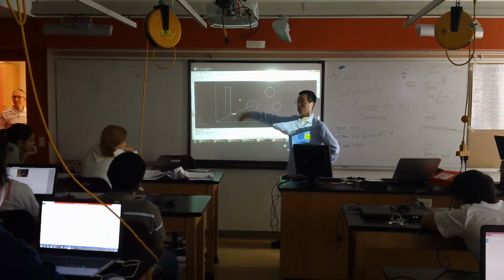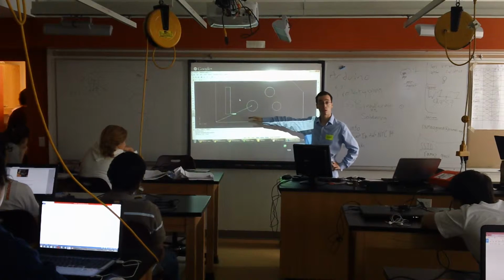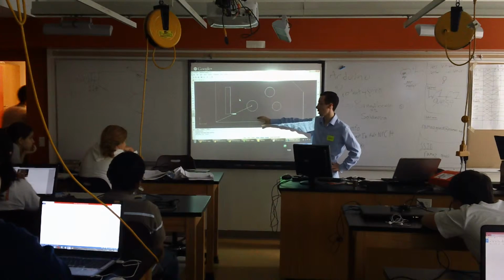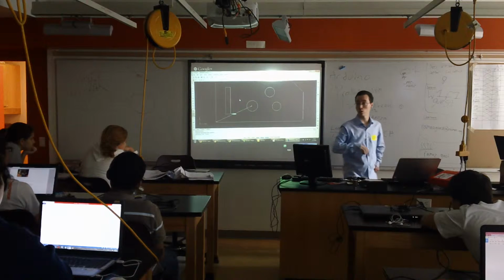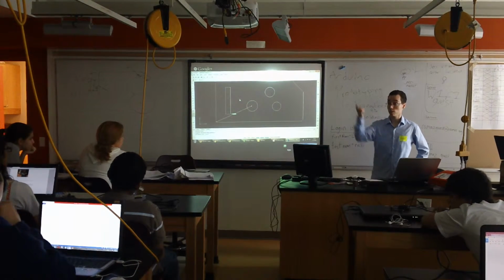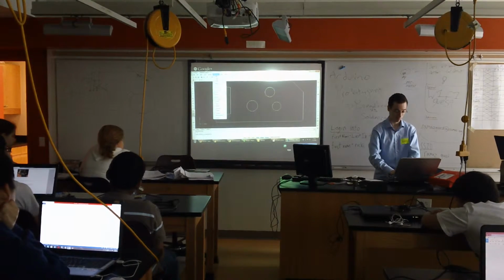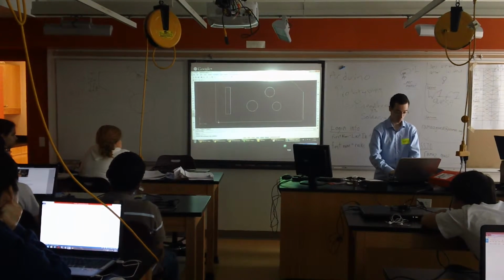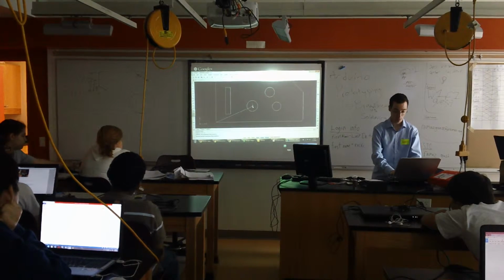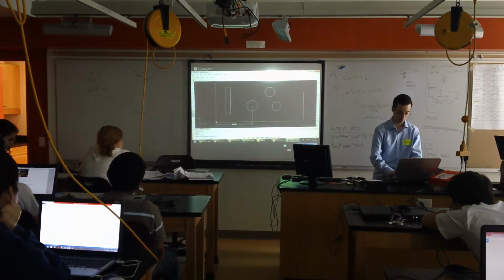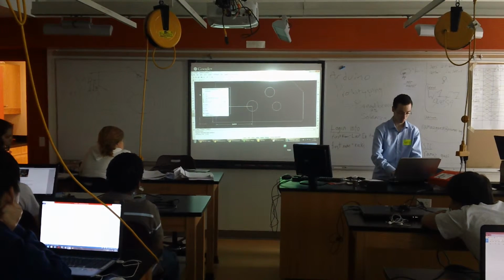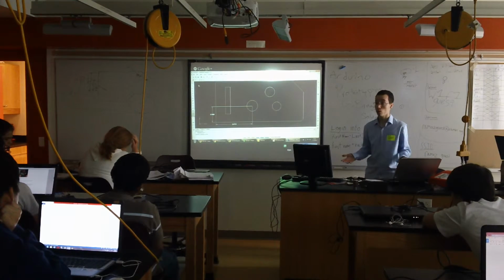I could give a length, and I could give an angle from this. That's not how we normally do it. There are cases when it makes it clearer, but in general, what should I do instead? You'd want to go to the right and give it a dimension. Right. So instead of that, I'll do Dimension Linear. I'm starting from my datum point up here, and I'll give X, and then I'll do it again. Start from here, and I will give Y. Great, okay. So now I know where the circle is.